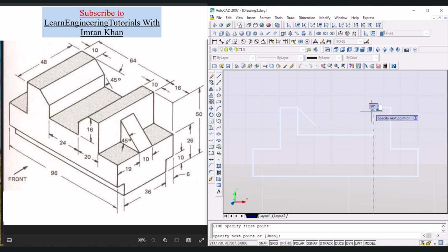Press enter, click. Now in this direction we can give any arbitrary length, so let it be 15, tab, and this time this angle should be 225, enter. Press escape.